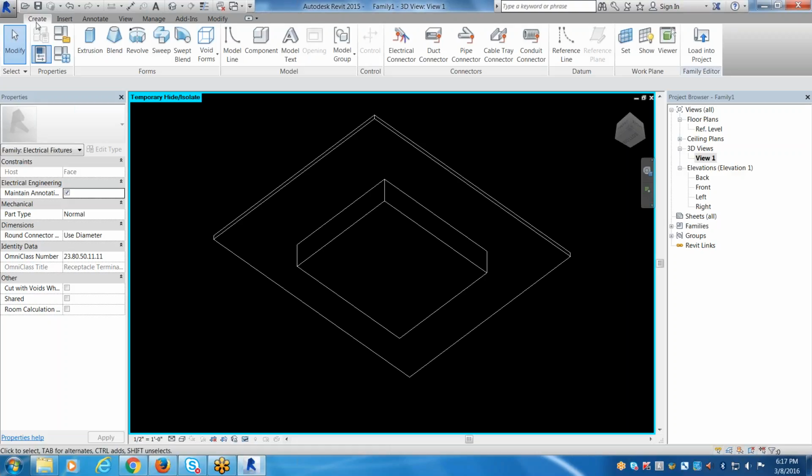Whenever you create something in Revit, in order for it to interface with the rest of the project, it needs to have these connectors, one or more. If you think about a condensing unit, it's going to have electric power, it's going to have air ducts, it's going to have condensate pipe drain connections, it's going to have all of that stuff. So some have all, some have one, some have none. Some things don't have to have any. This table, chair, easel, right? TV has to have connectors.